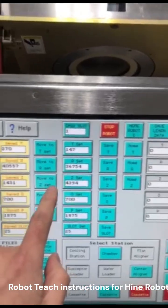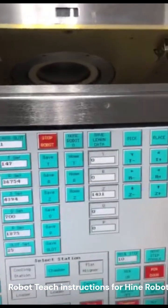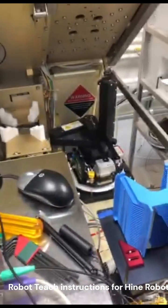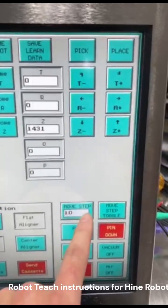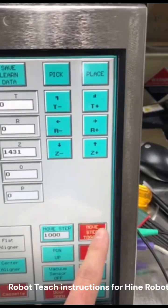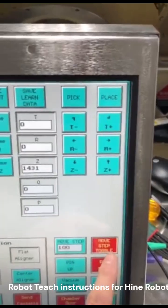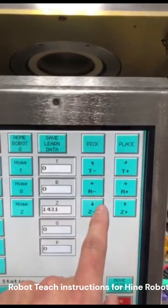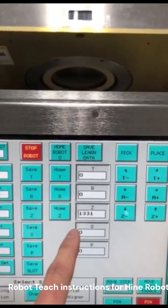You first need to move to your save Z. Notice how this Z value has now changed, although the actual robot may or may not move. Now you can toggle your move step: 100, 1000, 1. Let's try 100 in this case. Let's say it was too high to begin with. Then we lower it here. Z down. Notice that it went down by 100.